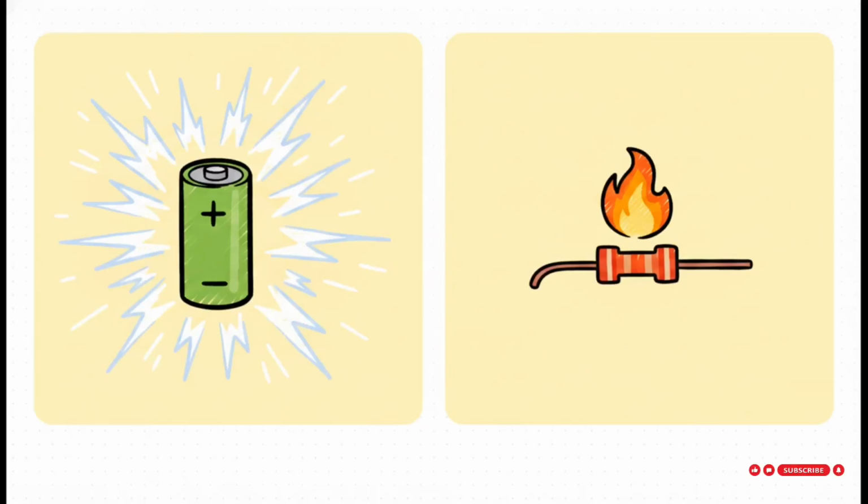All right, so we know the peak and we know how to grab a snapshot. But how do we summarize the wave's overall effort over time? Well, in electrical engineering, we've got two main ways to tackle this. First, we have the average value, which tells us the steady current that would transfer the exact same electrical charge as our AC wave. And second, we have the RMS value, which is the steady direct current that would produce the exact same heat power. So charge versus heat.